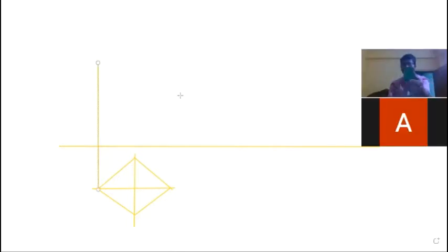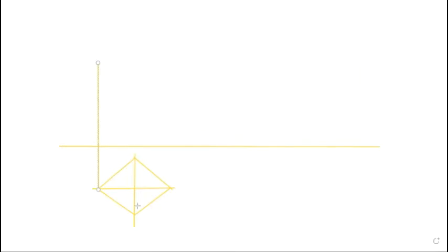And so what will be the front view? If you see the front view, basically in front view, if the position will be like this, you see these two edges, and this line, and these three lines you can see. So what we'll do for this, each point we draw the projection line. And this height will be the 56 millimeter from the XY.